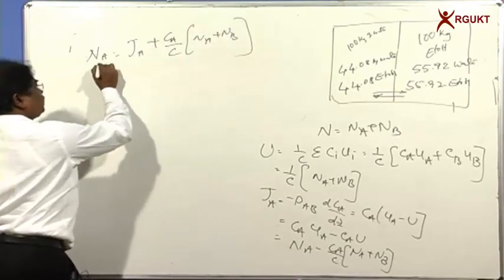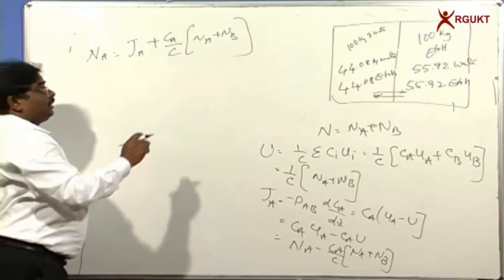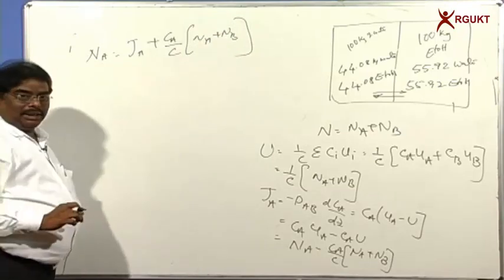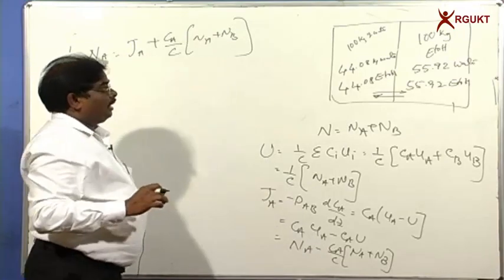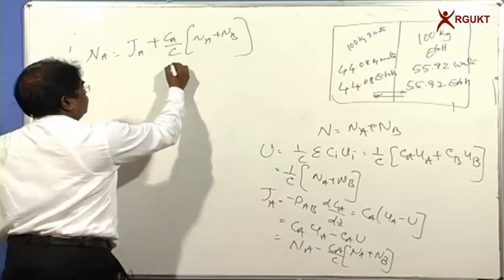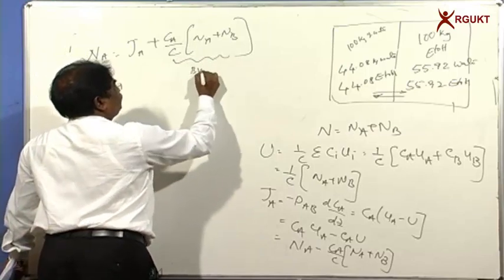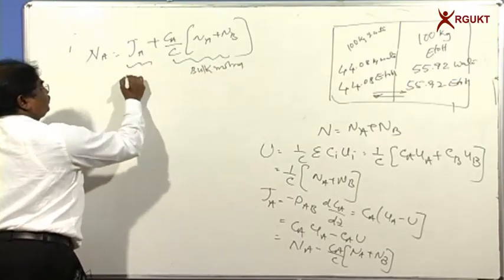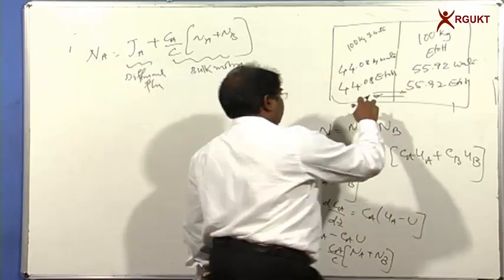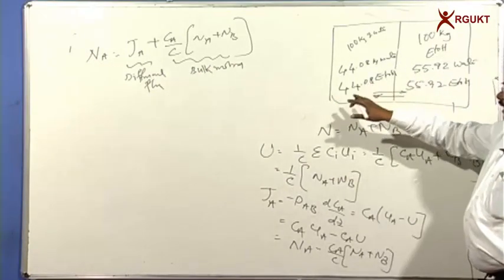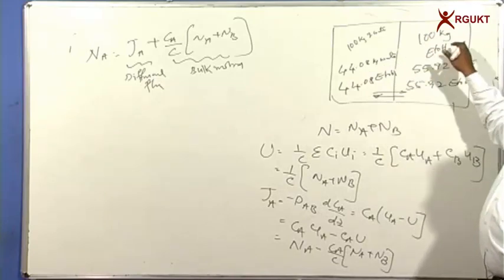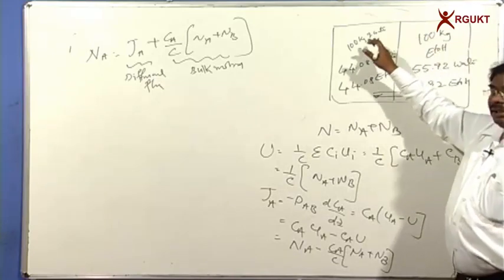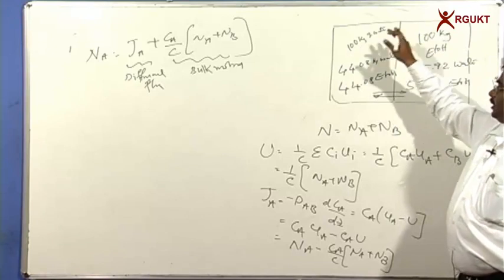So the flux of species i is equal to a diffusion flux, which occurs because of molecular diffusion, plus a total flux term, which we call the bulk motion. So when you remove the partition, suddenly there is a bulk movement of water from the water side to the ethanol side, and ethanol flows from the ethanol side to the water side.